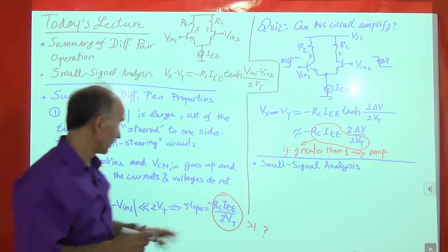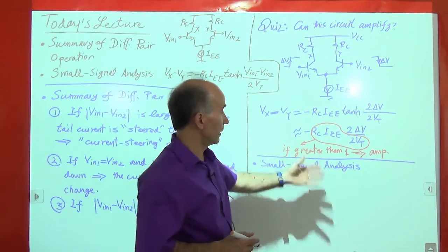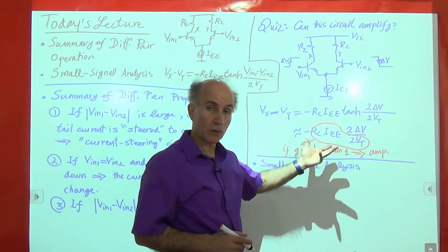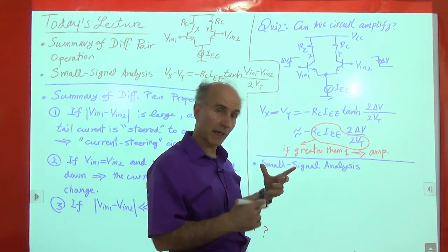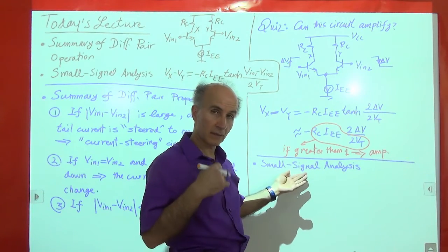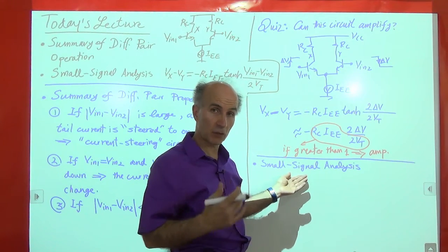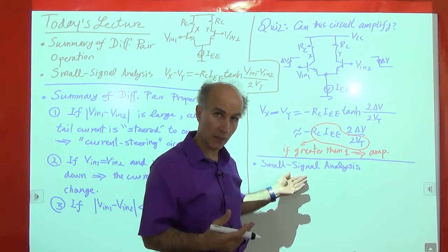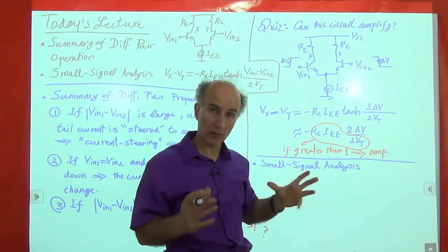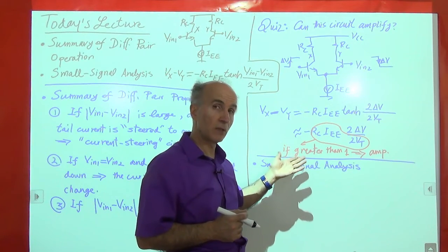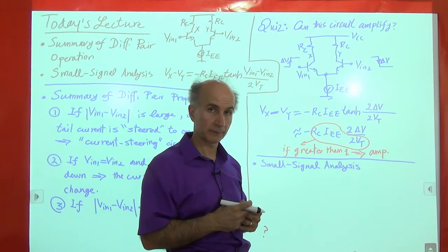In fact, yes. Here, we made that assumption and found the slope. Here, again, we made that assumption and we found the gain, right? So it seems redundant to go to small signal analysis. But we will see that this analysis gives us additional tools for analyzing more complex differential amplifiers, differential pairs. Not every differential pair looks as nice and as simple as this, right? There are more complex ones. So in some cases, we do need to be able to perform this small signal analysis on these circuits.